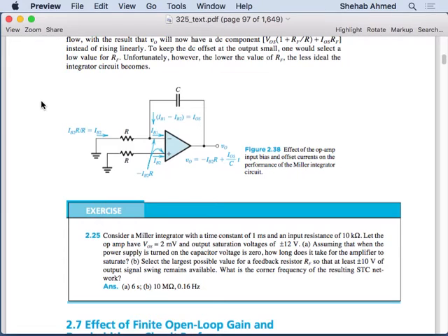It's going to be very difficult to eliminate it completely because of the matching of resistors. But in the worst case, you are passing through a portion of the offset voltage. Not even the full offset, a portion of the offset voltage is going through. So we're not amplifying the offset voltage. So that's great. Otherwise, without trying to do something about it, we were passing the offset voltage magnified through the amplifier, which was a problem.